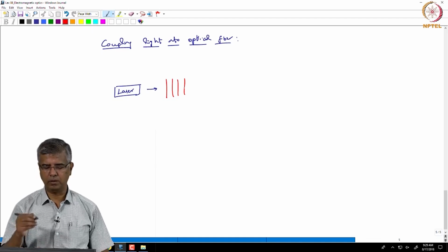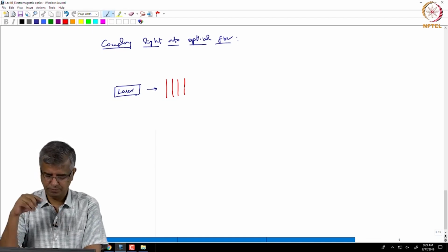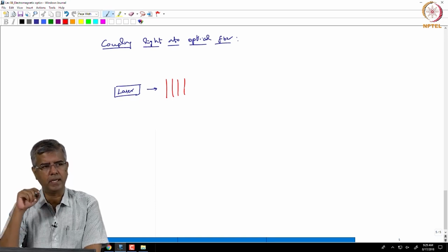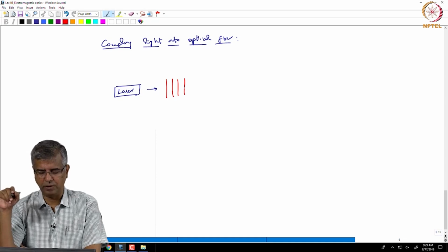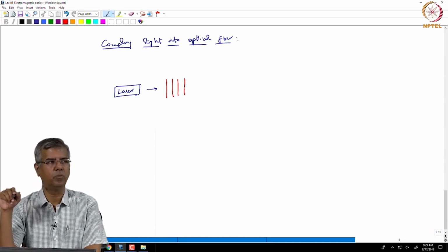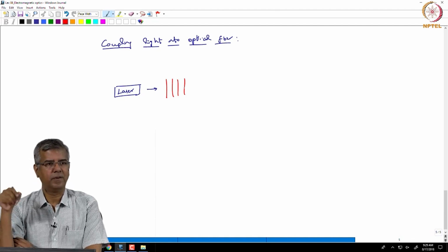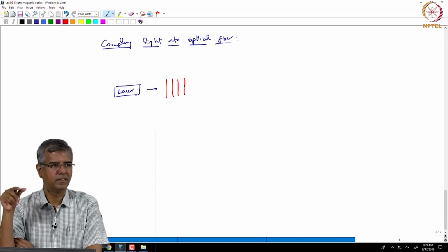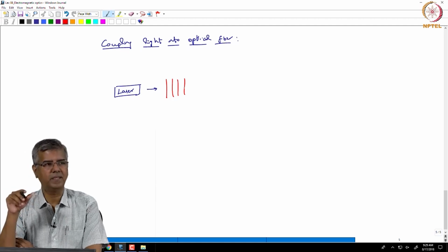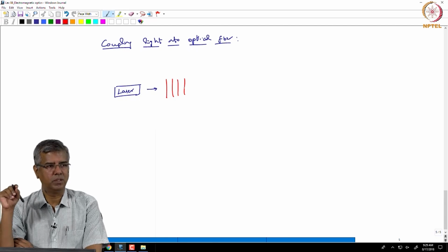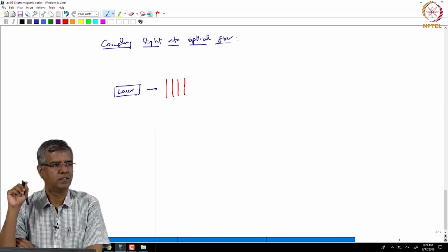The laser that we have has a radius of a few millimeters, but then it has to couple into an optical fiber. Let's say we are coupling into a single mode optical fiber. Okay, what is the size of a single mode optical fiber for the wavelengths that we are considering? It's in the order of a few microns, right? So a few millimeters need to be fitted into a waveguide which is a few microns.